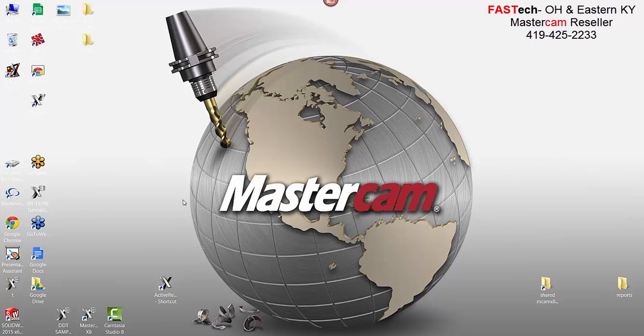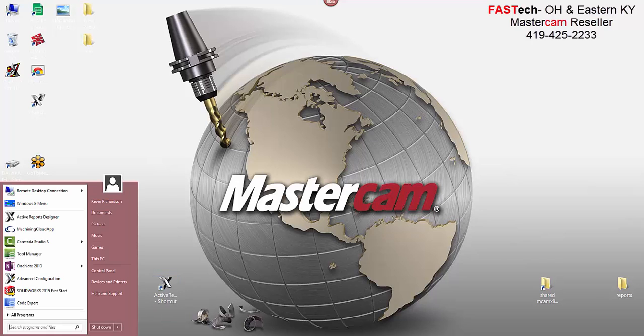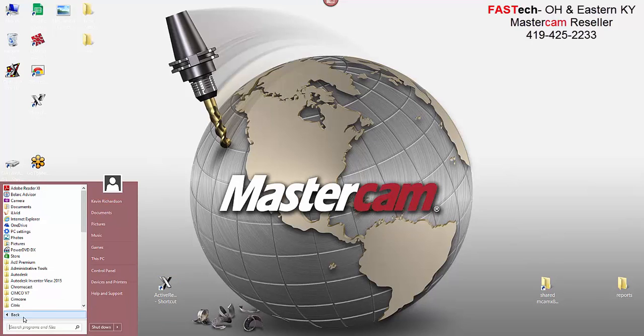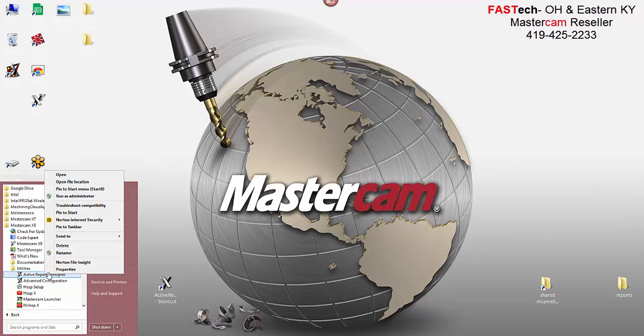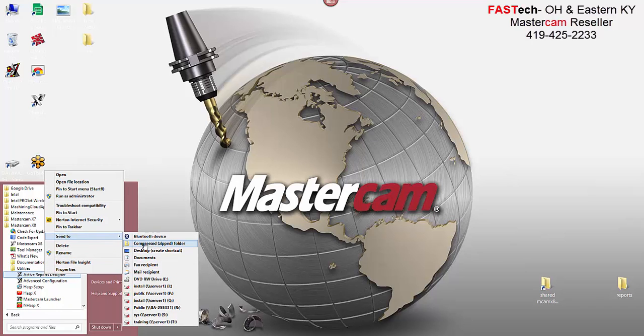How do you get the active report? You'll notice that I have a shortcut that I placed in here, so it's always easy for me to grab my active reports so I don't have to go through a series of steps. When I go to Programs, I'm going to start with Mastercam standalone version, Mastercam X8, and I'll go into Utilities. Now in Utilities, you'll see where I can click on Active Report Designer. If you right click on it and tell it to send to desktop, you can grab it in the future very quickly.